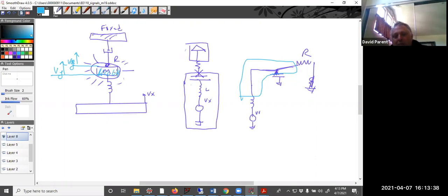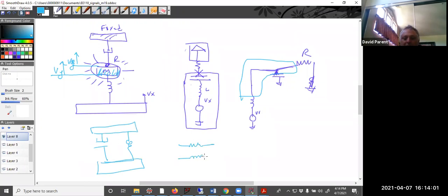But that's the thing. If I have the damper like this and the spring like this, those are going to be in parallel, however I connect them, whatever's connected there. But a mass is one end is tied to ground no matter what, and then everything else connects to it, because that voltage represents the velocity of the mass. It's kind of like whether I'm on that end or that end. And this thing has no dimensions. It's a dot, right? Does that help?